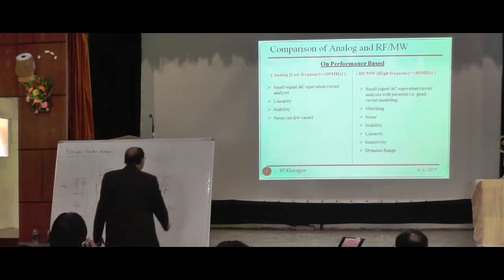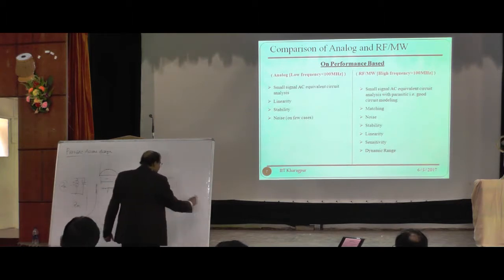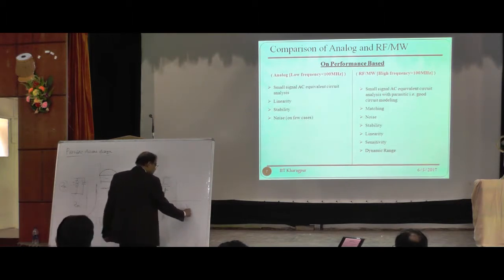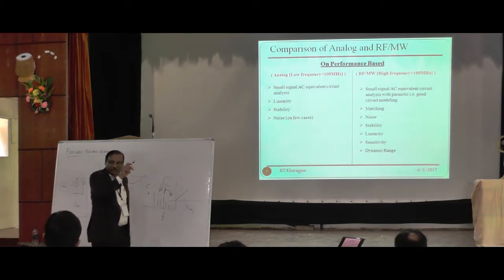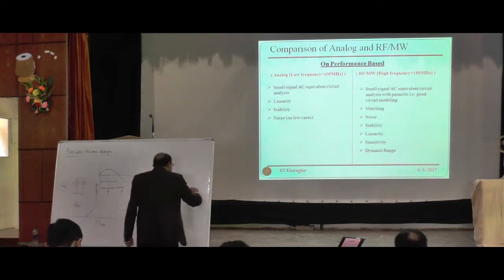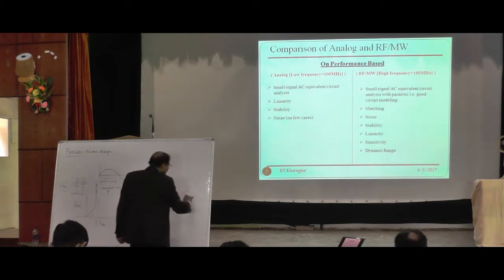So if you look at an amplifier, linearity and nonlinearity, what will happen? This is my input and this is my output. Initially, when it's a linear region, I need some kind of linear gain, right? After that, what will happen? It will be lowered or it will go up? Conservation of energy tells us the amplitude will lower because the energy will now be distributed across other harmonic components. So instead of continuing along the linear path, it will drop.